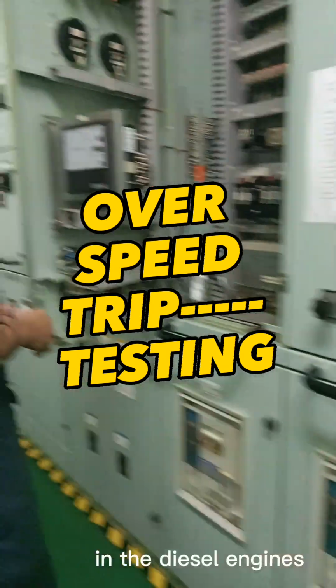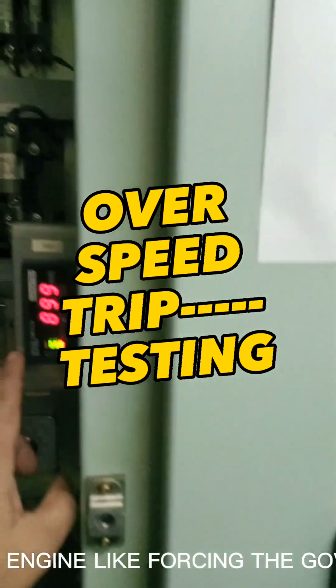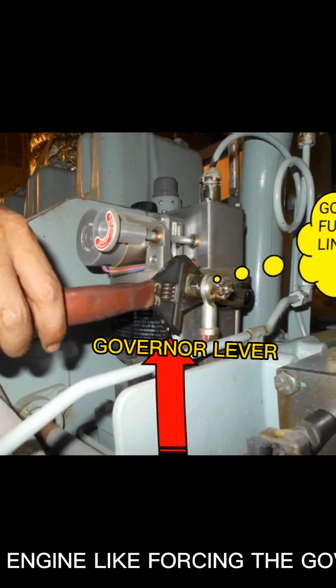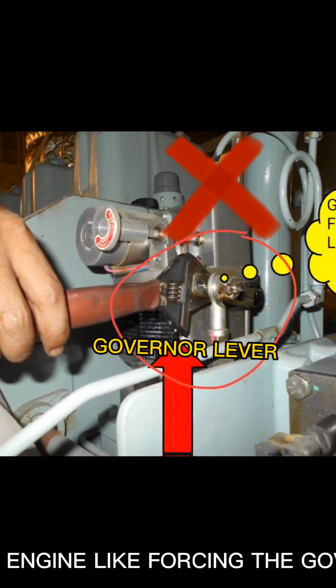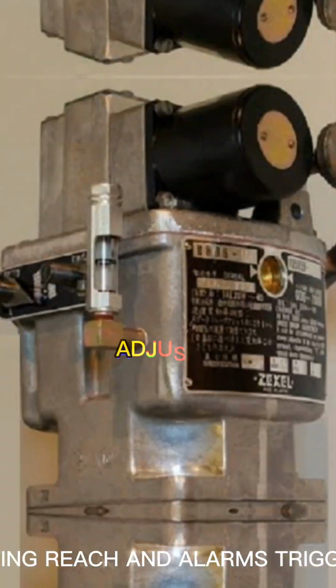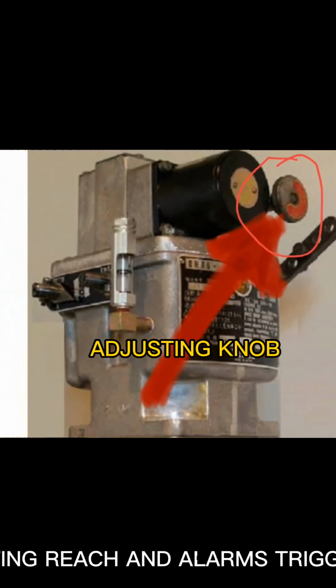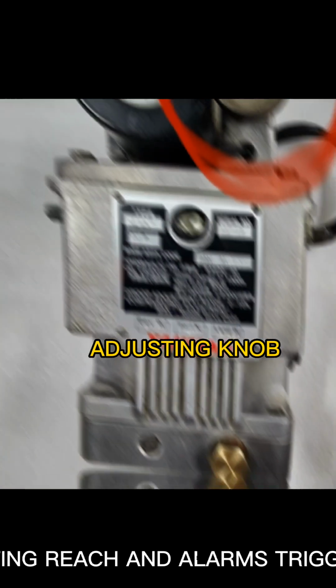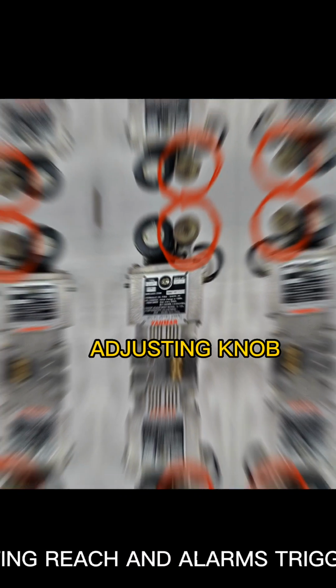In diesel engines, there are many ways of testing the overspeed trip on an auxiliary engine, like forcing the governor to increase until the overspeed setting using the governor lever. Possible but not safe. Another method is by adjusting the control knob until the overspeed setting is reached and alarms trigger. This is also possible but inadvisable, but can be done if there is no other choice.